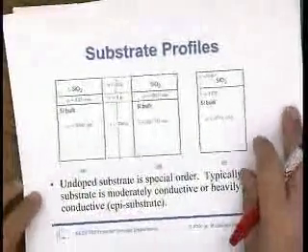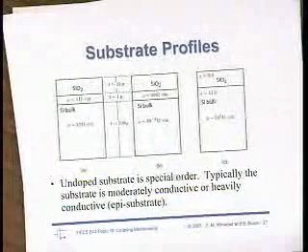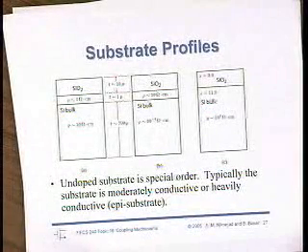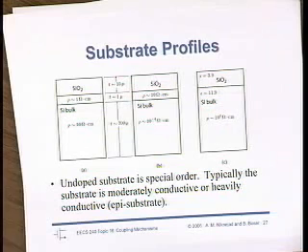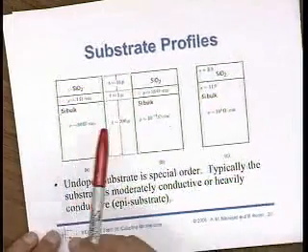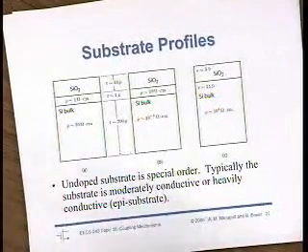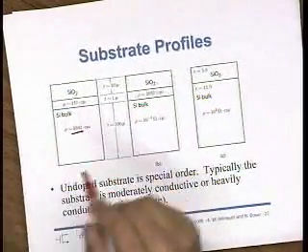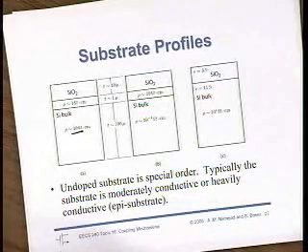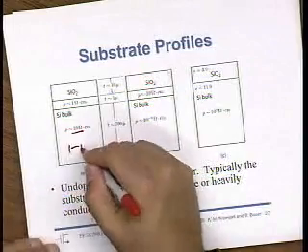It's also important to ask yourself, what kind of substrate am I using? We're not used to asking this question, but it's very important to know the resistivity of your substrate. And there's 3 standard flavors for bulk CMOS. So bulk CMOS comes in kind of like vanilla CMOS. People might call it bulk CMOS, where the substrate resistivity is on the order of 10 ohm centimeter. That might be a little more, a little less, 10 to 100 down to 1. So maybe 1 to 100 is a typical range.